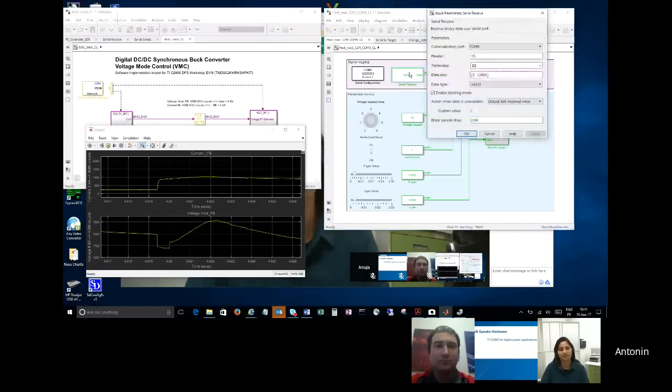And here, basically, it wouldn't be possible for Simulink to read one data point at a time. So I'm actually reading 12,000 data points, and 12,000 times 2, because I have 2 UINT16s to read. So I'm buffering 12,000 of these 2 signals, and I'm reading every 60 milliseconds. So if you do the math, that's 5 microseconds worth of data buffered into 12,000. So Simulink only has to read once every 60 milliseconds.